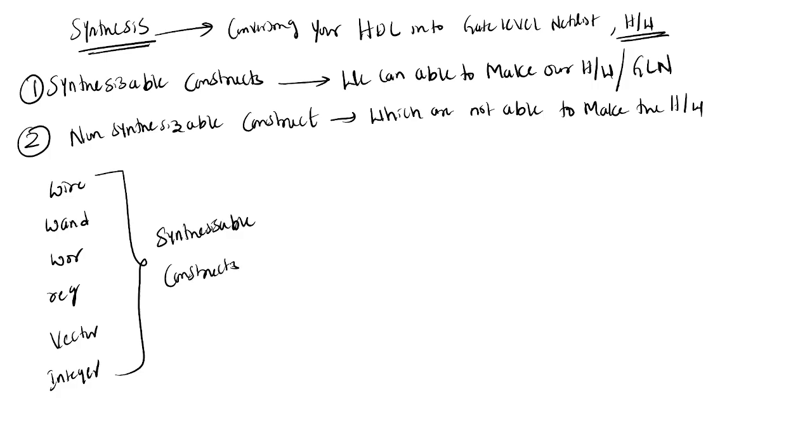And next, float, or we can call it real, and time. Mostly time we use only in the test bench, not in the design. So these are non-synthesizable constructs.